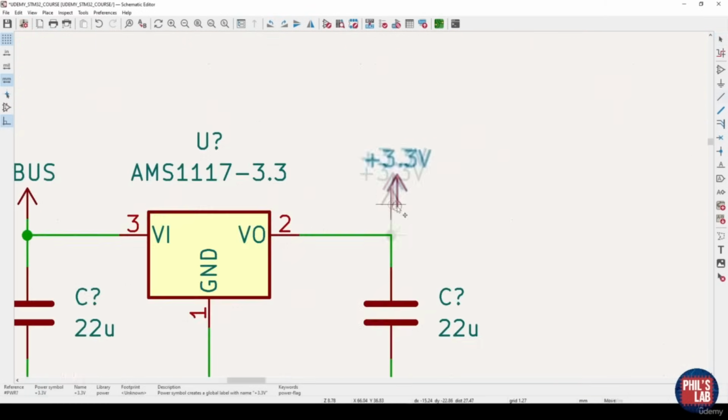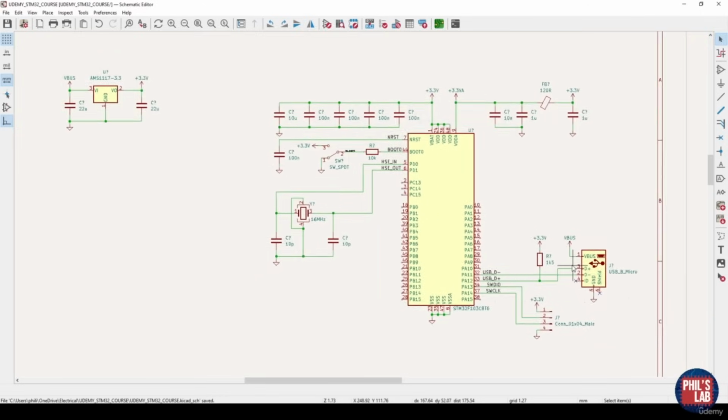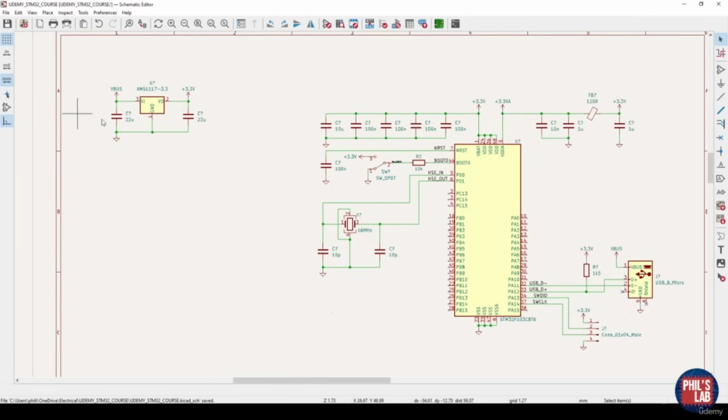volts over here. Now, USB power rails, so coming from the V-bus line, are typically very noisy, and it's good practice to perform some additional filtering, because this capacitor won't do next to nothing, in terms of a ferrite bead, inductor, or so forth. For this very simple example, and because this design will work even without filtering, we'll just leave it as it is.